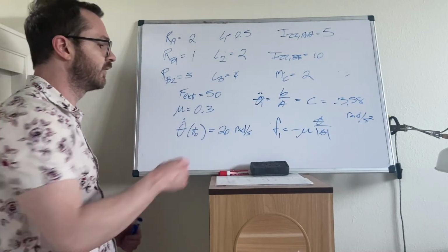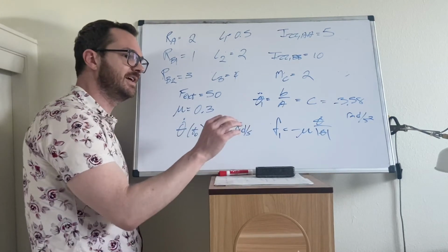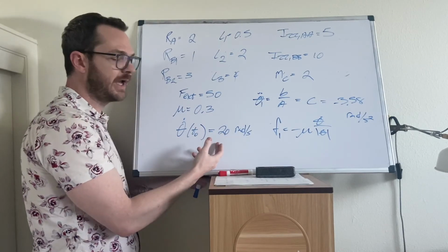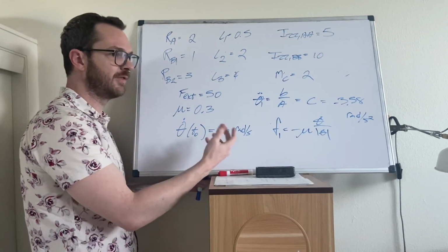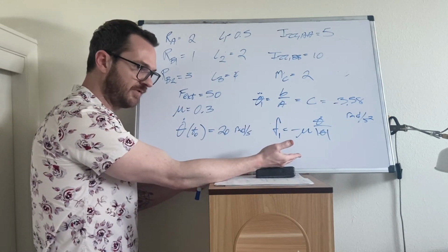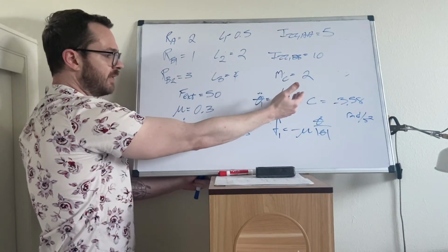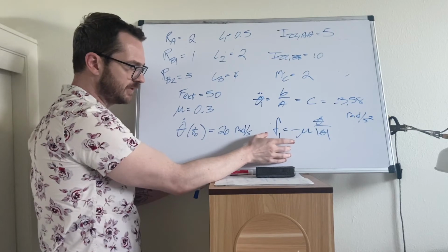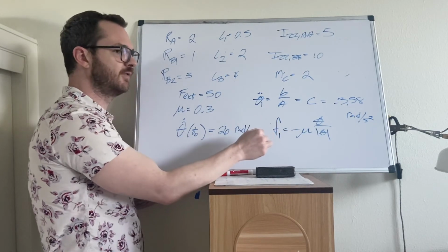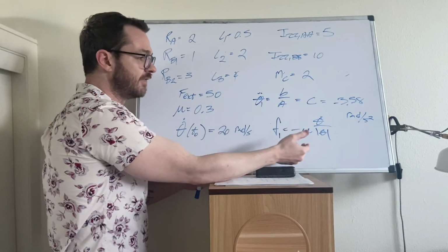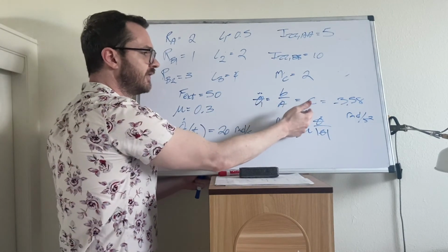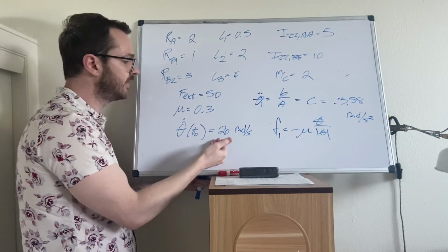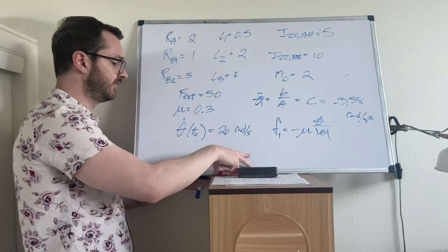The friction is a function of the sign of theta 1 dot, not the magnitude of theta 1 dot. That means if I had changed theta 1 dot, going from 20 to say 30, the magnitude of the friction would have been the same. And if I don't change any of these parameters, then the acceleration remains the same. I selected this friction model specifically because it is not a function of the magnitude of theta dot. The acceleration then is negative 3.58 when we're at 20 radians a second, at 10 radians a second, at 3 radians per second.